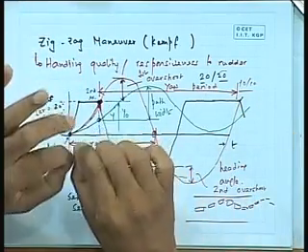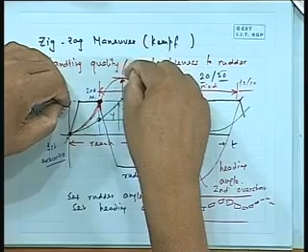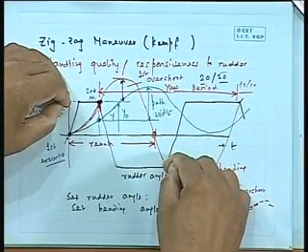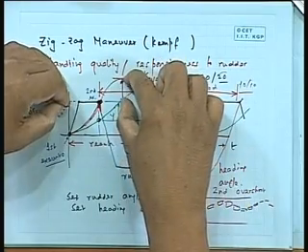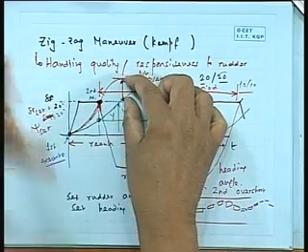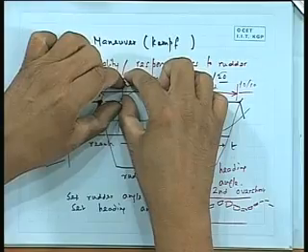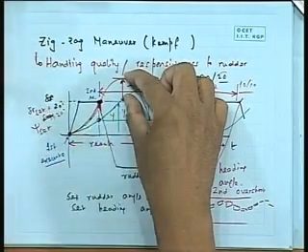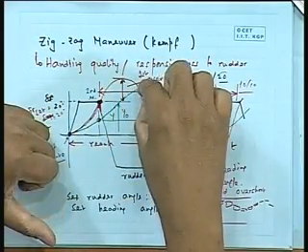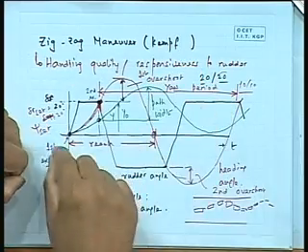Understand that basically what you are measuring is, you keep on turning the rudder this way, that way. You find out that the moment I change the rudder, after how long, number one, the ship's heading turns back and comes to 0, and how much more it keeps overshooting in the same direction. This overshoot tells me how much it will keep overshooting, heading angle as well as path width, and what is the time taken.